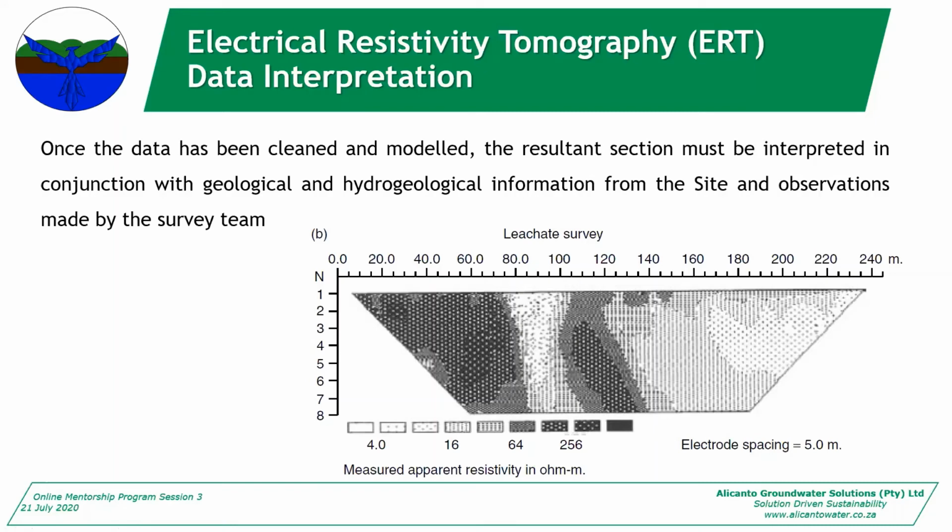Well, you said it's a leachate, so I would say, I've not worked with something like this before. But I believe that your anomaly that has a low apparent resistivity would be more a solid rock with no, how can I say, flow in it. So no contamination, if you're picking up contamination with this survey.